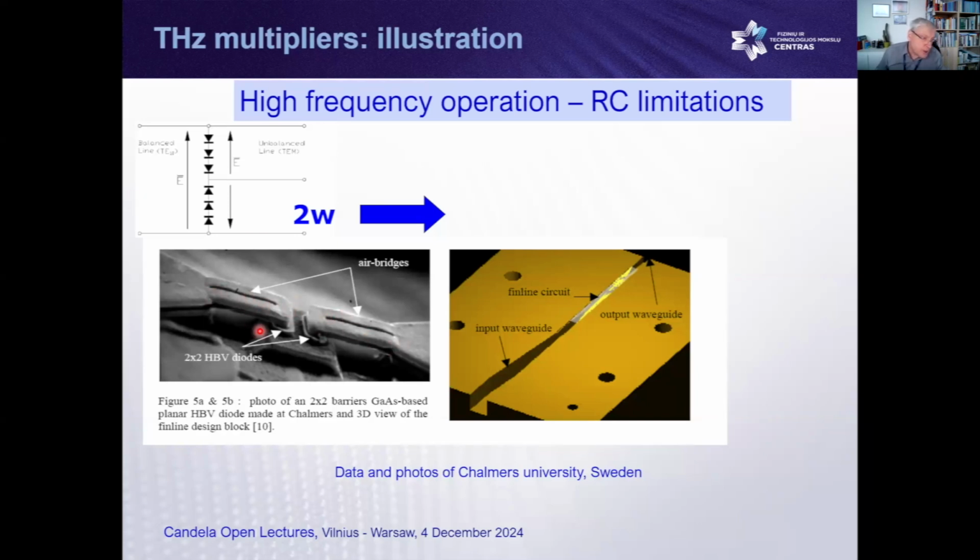They have something like a bridge. There is nothing below, because epsilon, which is the dielectric permittivity of the material, is sometimes removed just to reduce the capacitance of the structure. Usually for gallium arsenide the dielectric permittivity reaches 12. It means if I remove gallium arsenide from the game, I can win 10 times higher frequencies. These are big numbers and it needs to be done. So it's one of the technological ways to do that.